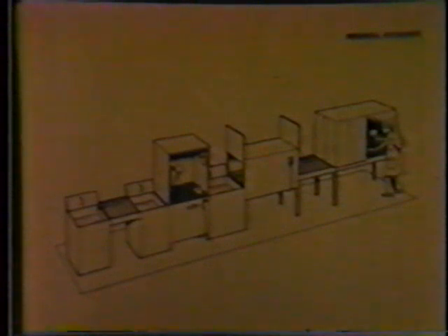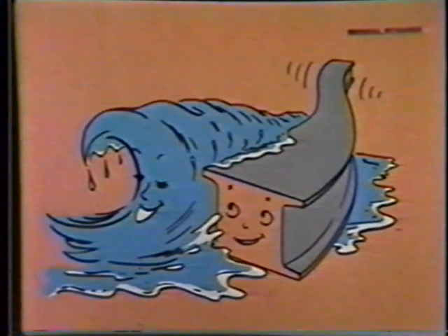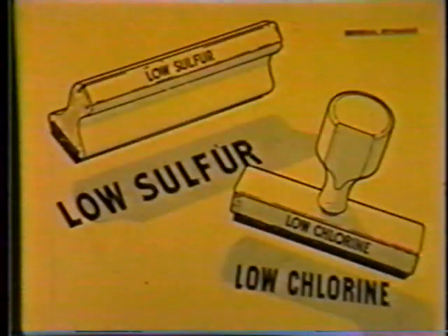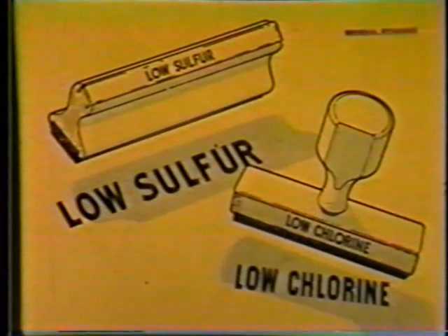Stationary or tank systems are for production testing, particularly when there are large numbers of parts. Usually, fluorescent penetrant is used. Penetrant materials and test specimens must be compatible. Sulfur and chlorine adversely affect certain nickel alloys, stainless steel, and titanium. Testing requires penetrant materials low in sulfur and chlorine.